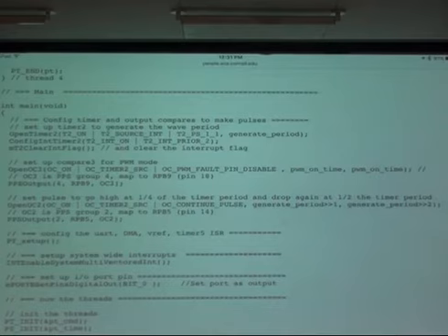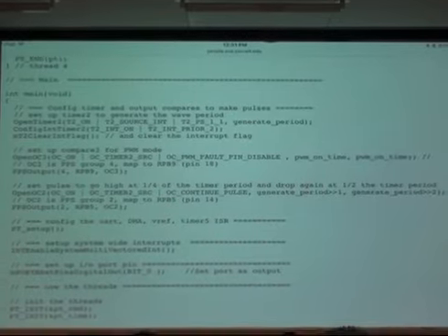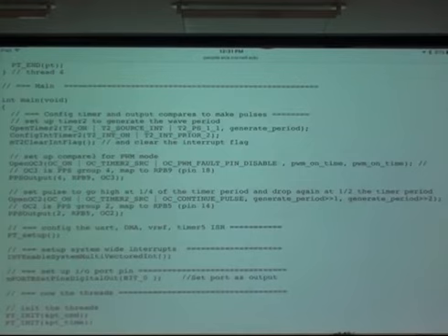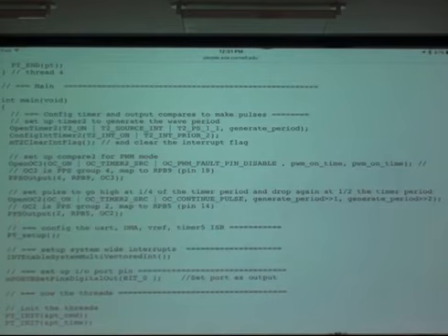Then you might want to turn off the voltage to it. So this is a fault detection to avoid destruction of hardware. We're not using it. Seems unlikely that you're going to demolish anything with a 100th horsepower fan. But in any case, there's no measuring circuitry that you could feed back. So if you had a circuit that would indicate a motor failure, you'd input it to the fault pin.